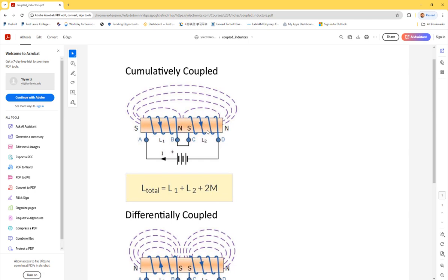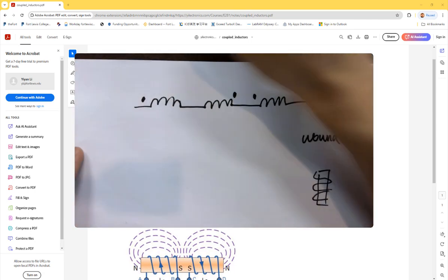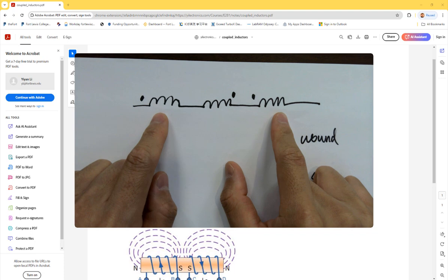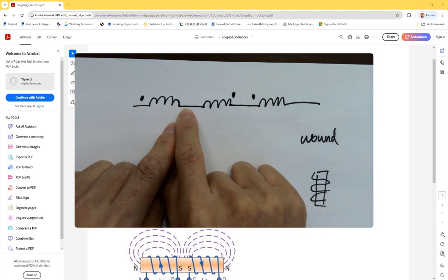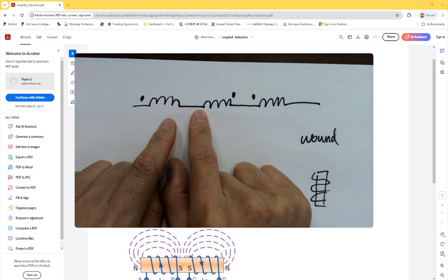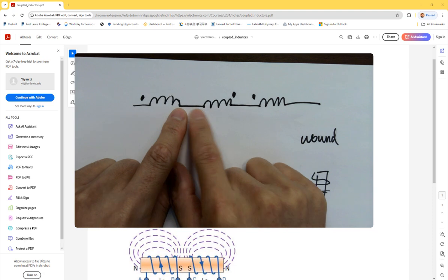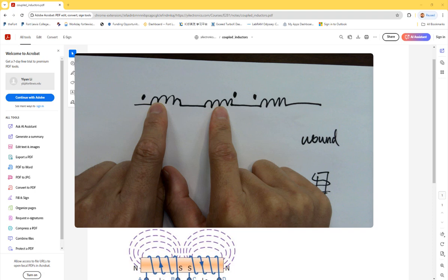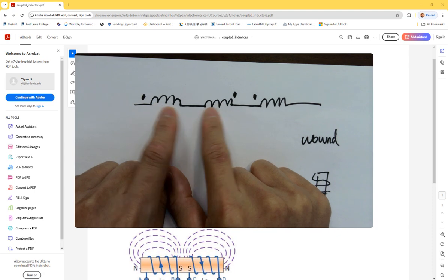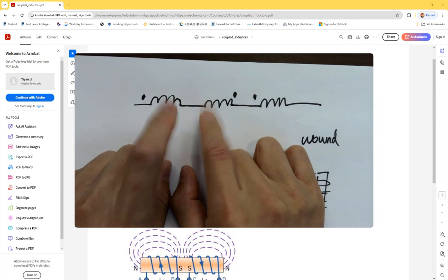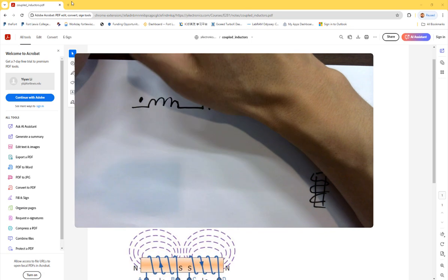So if you just look at the schematic, could you tell if they are physically placed next to each other or not? It's just showing an electrical connection. It's not showing the physical connection. Does that make sense? In a schematic, you can draw a wire, but that doesn't mean they are placed close enough to generate a certain mutual inductance between each other. So a schematic's not showing physical placement. I'll show one quick example.